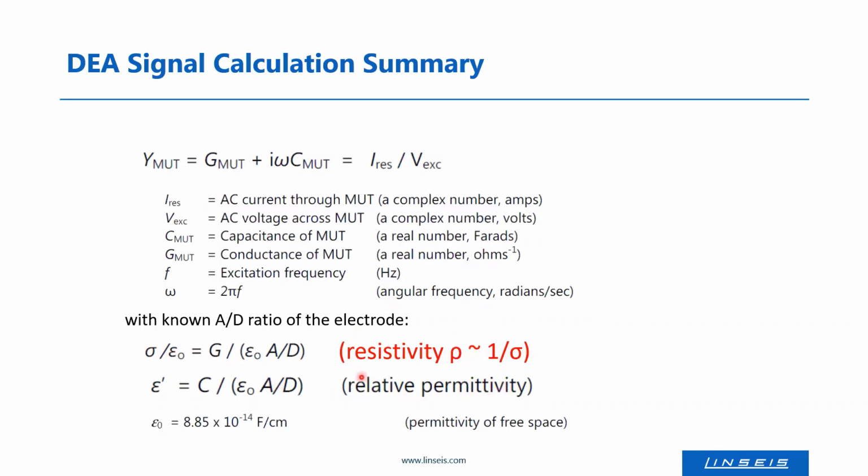The permittivity, to mention that again, is due to dipole rotations during the measurement, and the conductivity or resistivity is caused by the movement of ions in your sample. And this is what we want to have. And this resistivity or conductivity monitors the cure.